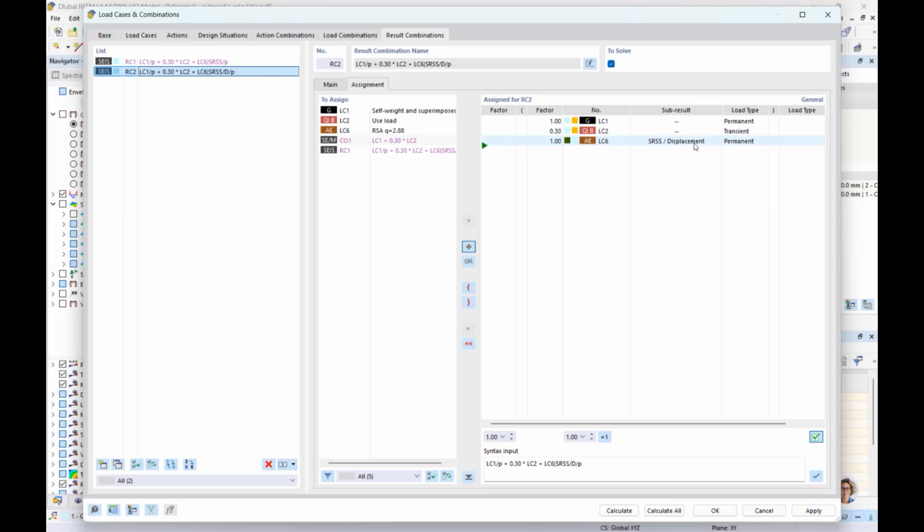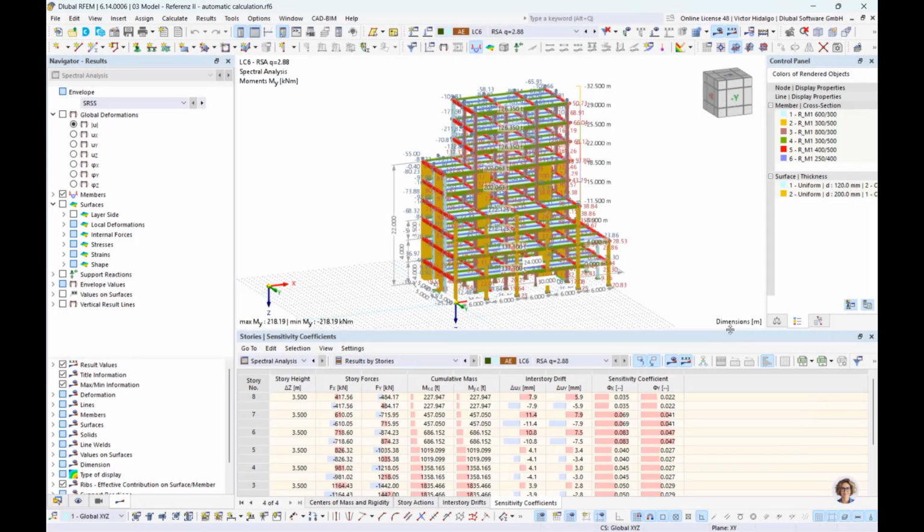Of course, Eurocode has the multiplication Q sub D directly, but we saw an example from ASCE 7 where the multiplication factor is not exactly the division factor of the spectrum, no? So that's why each standard has a different approach. Okay, I think that's all on the side of content and this new development.